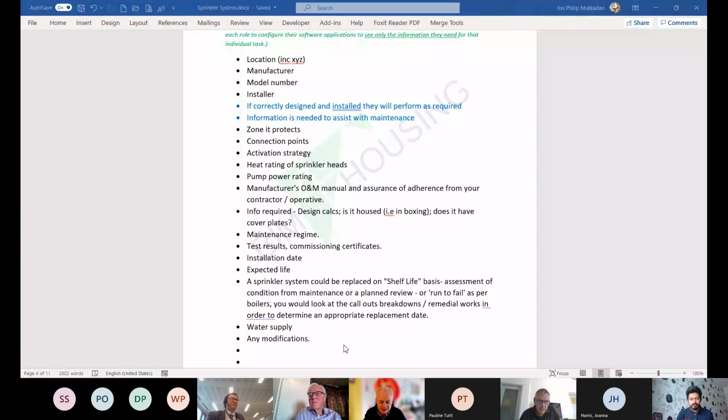But yeah, galvanized. Is this for dry systems, by the way? Yeah, it was dry systems. You wouldn't have very many of those in these buildings. Normally, they'd all be wet systems. But yeah, in a dry system, it's internally galvanized. You've got this zinc coating on the steel, and it's a different type of corrosion to just black steel corrosion. But it doesn't matter what type it is. It makes a hole in the pipe. And so that's what can happen.